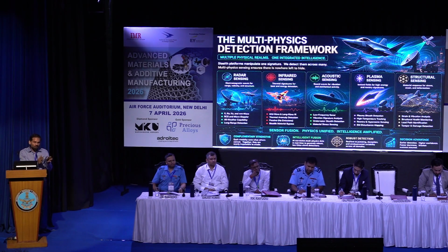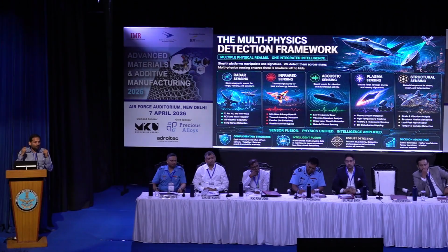So when we use the squeezer, meaning an artificial magnetic field on the rocket system, that magnetic field can control the thickness of the plasma. That is what I mentioned as the quarter-wave condition. A specific thickness of the plasma can cause destructive interference of the electromagnetic waves, and that destructive interference can cancel out all the radar signals coming to detect, so the radar cannot detect where the missile is coming from.